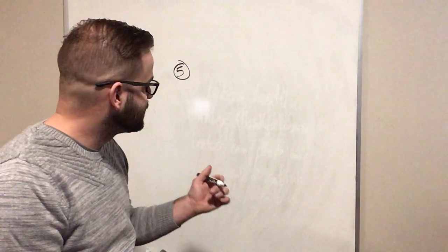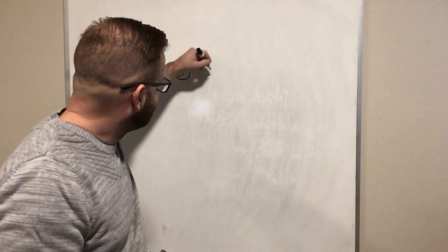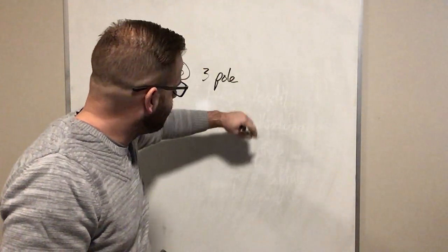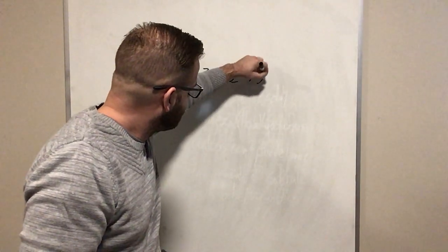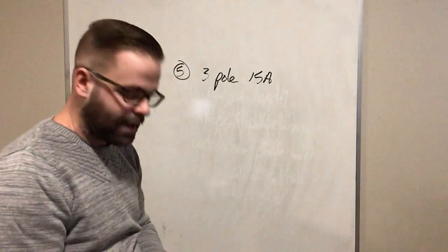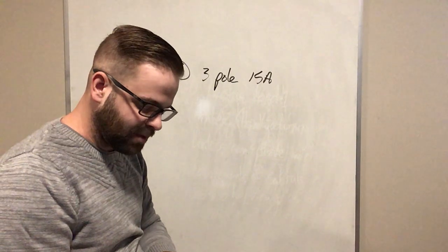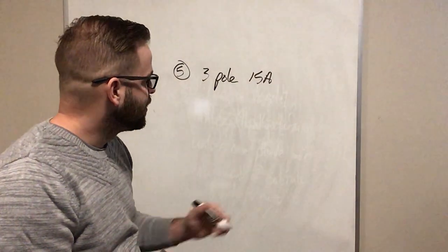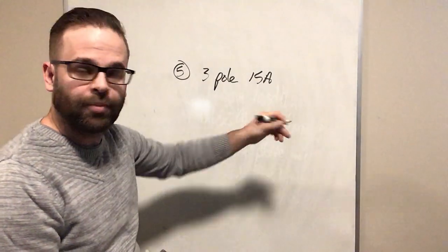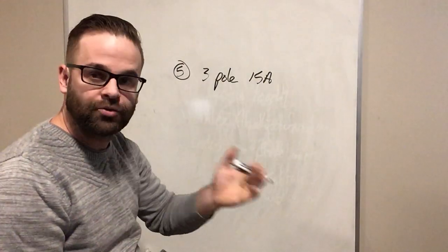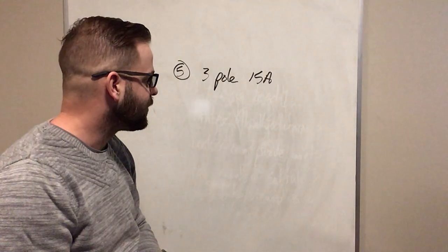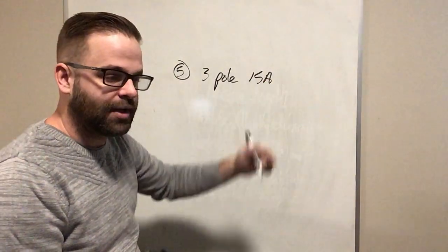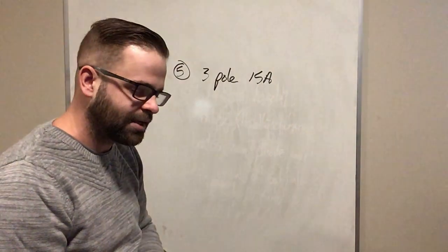So that is basically saying, let's say I have a 3-pole 15 amp breaker. It can be used at continuous operation at 100% of its ampere rating. A typical breaker would be limited to 80%, and 80% of 15 would be 12 amps, so that's typically what we'd see.